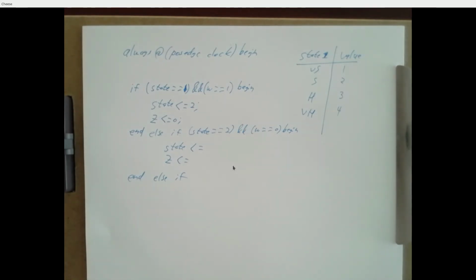So my suggestion is try to get a counter working, right? Just to figure out the details of the syntax of the always block, no semicolon after begin, and that kind of stuff. And then, I don't know, try to make a down counter that counts down. And then try to make a counter that goes from 2 to 7 and back to 2. That's a little more involved. It's got another if statement, right?